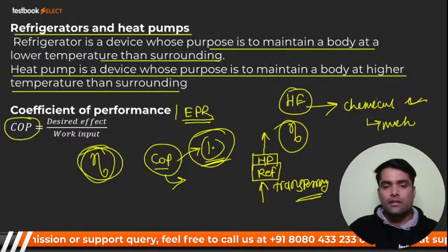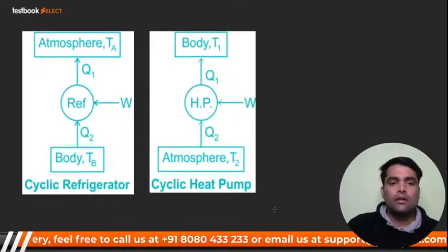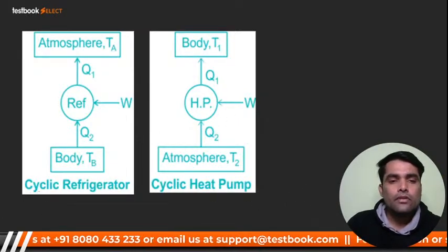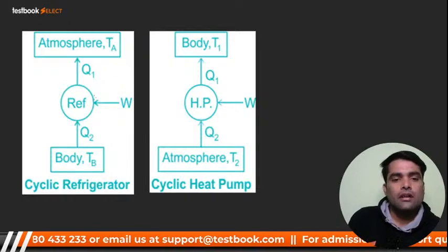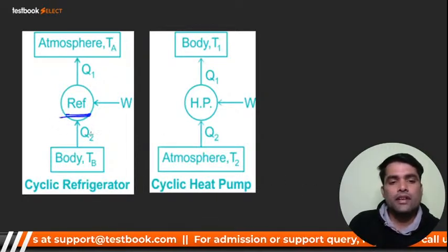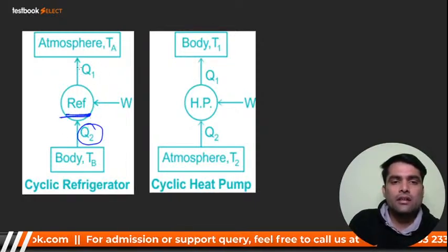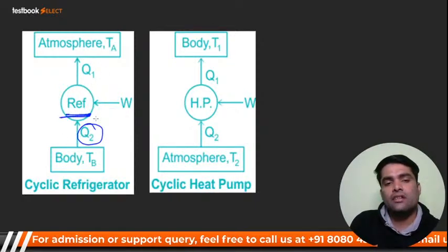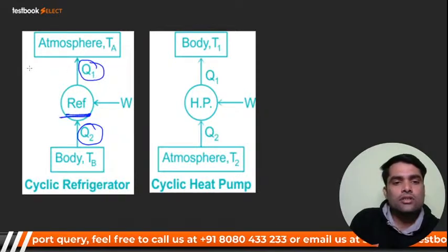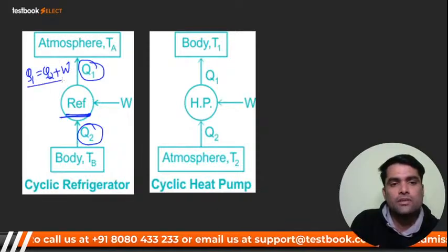See here, my dear. Look carefully. Now this is your refrigerator. It is taking heat Q2 from the body TB, and it is rejecting heat Q1. Q1 will be equal to Q2 plus W, as per the law of conservation of energy.